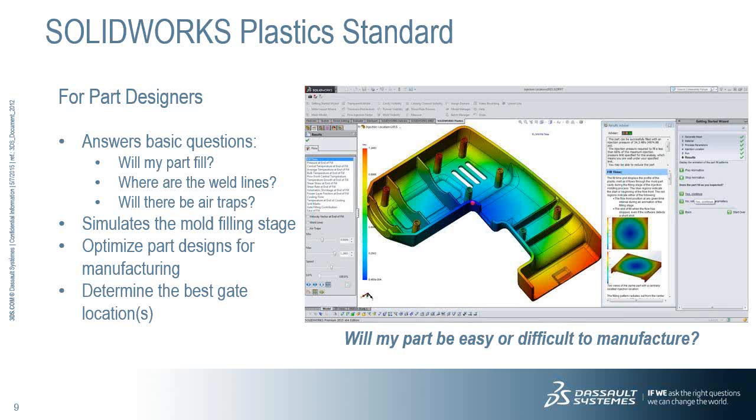And then it simulates the mold filling stage. I just want to know how many seconds, or how much time it would take to fill. And optimize part designs for manufacturing. I just want to see the manufacturability by testing the uniform wall thickness, or whether the drafts provided are proper, and also I can determine the best gate location to avoid defects and also get the fill in the required or stipulated time.